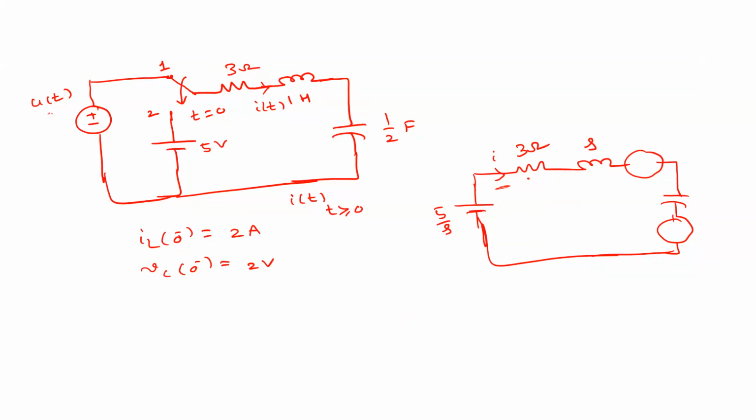So what is the initial voltage? L into its initial current, right? So what is this value? 2 into 1, right? It is 2. So what is the polarity? What is the polarity? Plus minus or minus plus? Just check it out. Check your notes once.